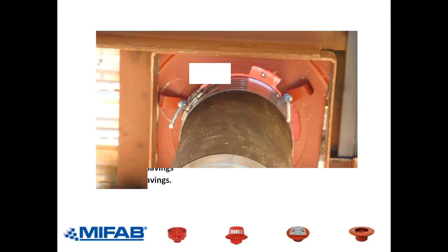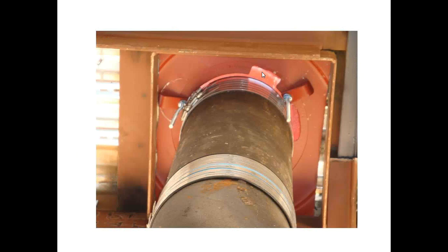So here's a good photo. Here what you have is the underside of the roof. You have the A2 body, and you can see 2 of the brackets bolting the bearing pan on the right, on the outside, to the body. So we bolted the body to the pan. The pan is fastened from the top of the deck. And there's no underdeck clamp there, no need for one.